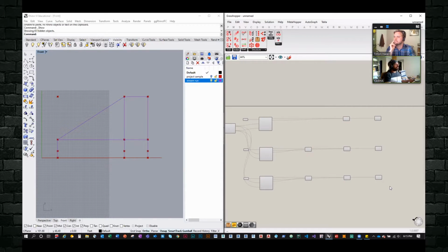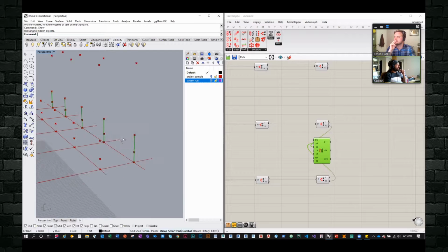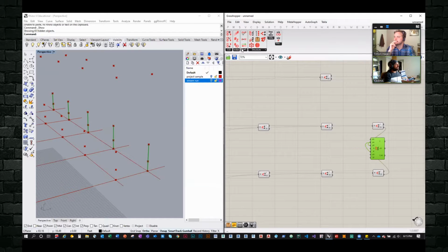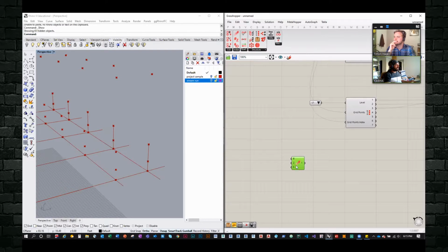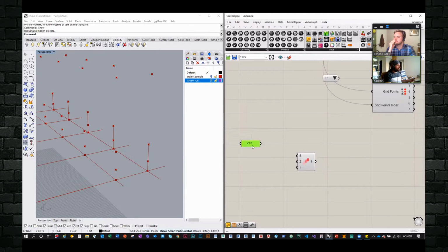So now it's time to connect the points to create the actual curved frame that will eventually translate to a Revit element. So I need columns, and this is a column cluster component that takes the points and the indices and builds a column frame. Now, the last bit to this is the base of the index. So I also developed a way to create a drop-down list of a base index. This requires a building or a site. So for example, I'm going to call this YouTube stream. You could call it whatever you want for your project specific.